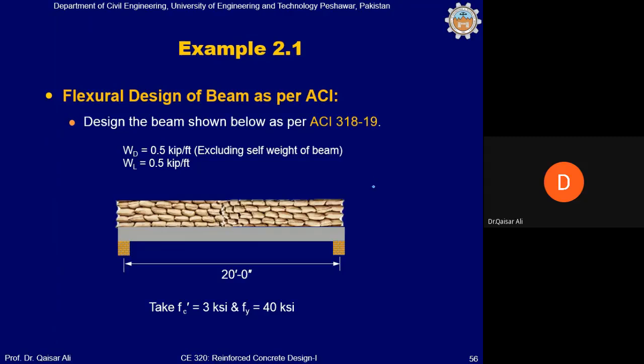If you look, we can idealize this beam by a simply supported beam like this, and this will closely depict the behavior of the actual beam. This is what is called idealization. And if, for example, we remove this support, what will happen? Can anyone tell?